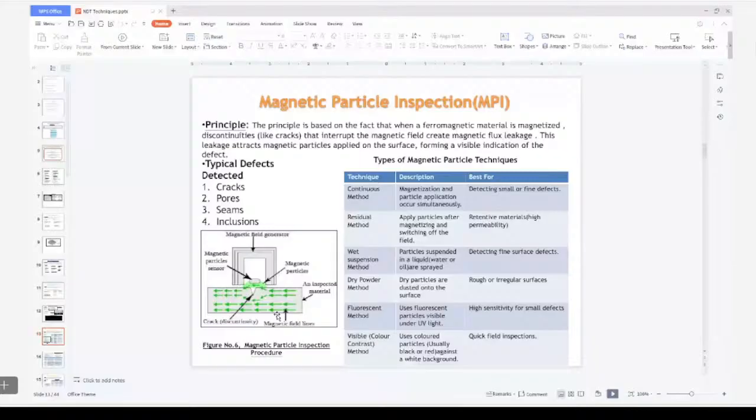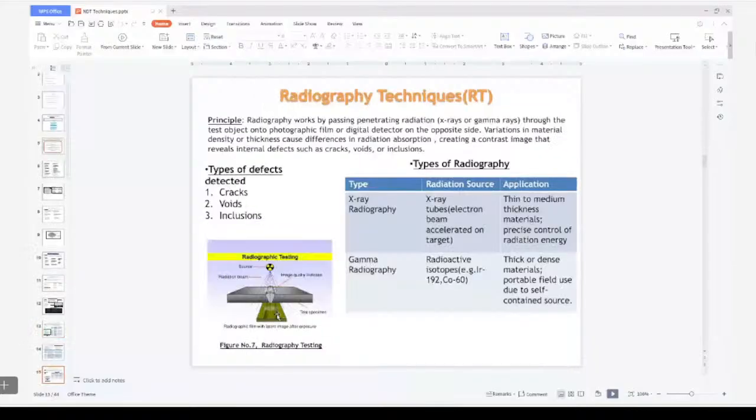Now we'll go to the internal defects. So far we have seen surface defects. Now we'll go for the internal defects, that is radiography. In internal defects, there are three-dimensional defects or two-dimensional defects. Three-dimensional means voids, porosities, segregations, shrinkage, and cavities, because these will give you much higher contrast. Okay. So the fundamental idea remains the same.